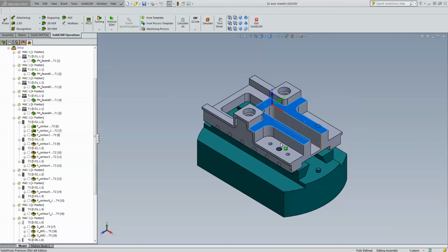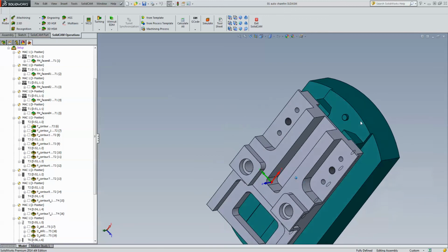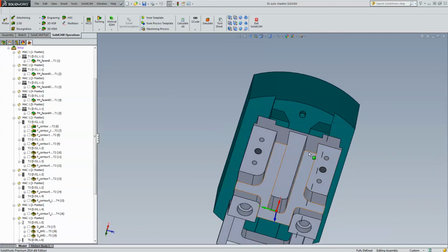It'll work on this surface, and if this surface was at a slight angle, it will work on that corner as well. Okay. To clear these corners, however, you would do that in your regular profile operation by rounding the corners itself. Or in this particular case, since it's a 5-axis machine, I'll just index it up to that surface over there, and then just do the chamfer operation on this surface over here.